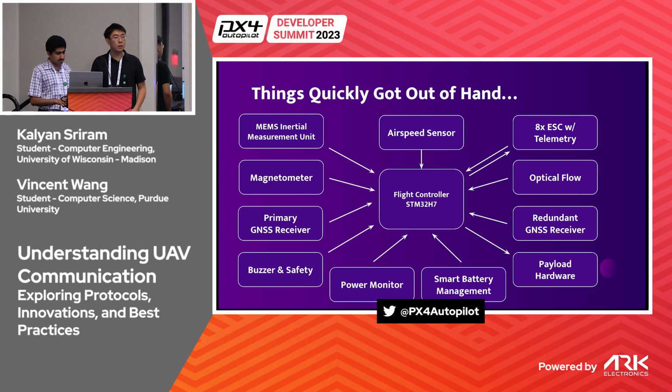And let's talk really quickly about those speed controllers. ESCs have microcontrollers on them because you need brushless commutation to switch the coils. However, for compatibility reasons, they still use that PWM encoding we talked about earlier. So you have a flight controller with a powerful microcontroller, taking a throttle set point, encoding it into this PWM signal, transmitting it, and then just to decode it again. This requires a dedicated line for each ESC, and there's no way for the ESC to send any health reports back.